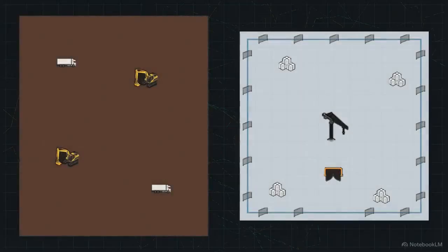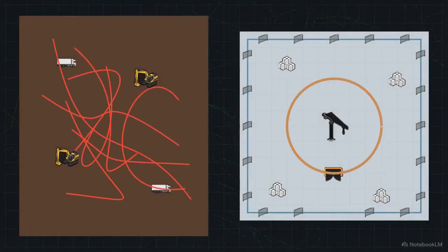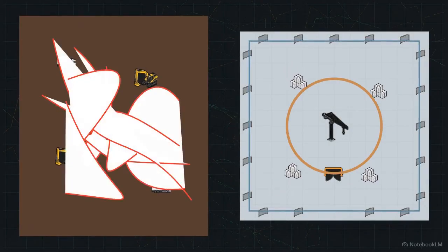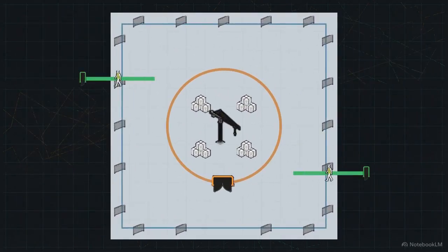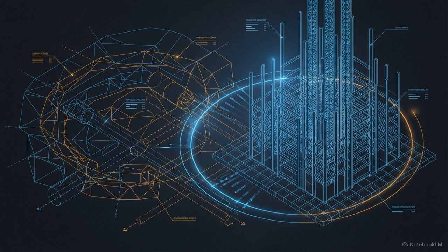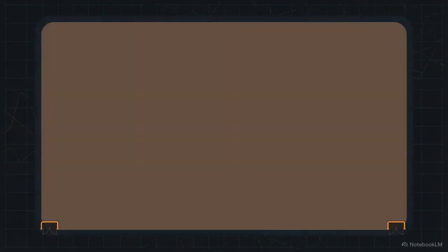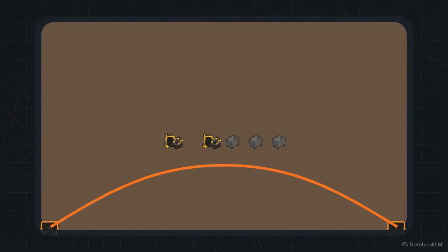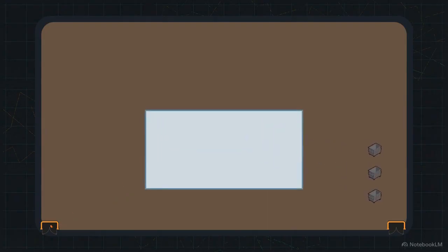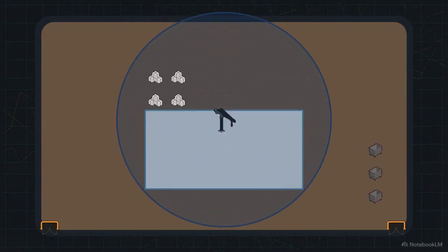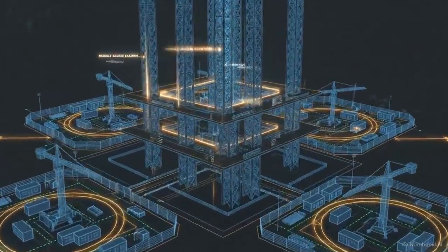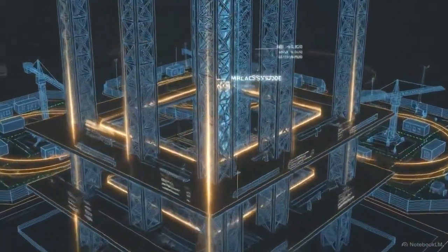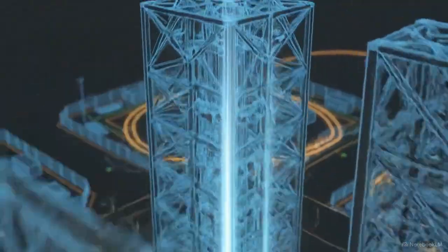Look at the final optimized map. We have taken that chaotic, unmanaged dirt lot and engineered it into a rigidly structured, color-coded production system. Keep in mind that site logistics are highly dynamic. A Phase 1 layout used for excavation will require entirely different staging and routing than a Phase 2 layout used for vertical construction. Because of this, you should save versioned copies of this map and update your laydown yards and flow paths as the project evolves.